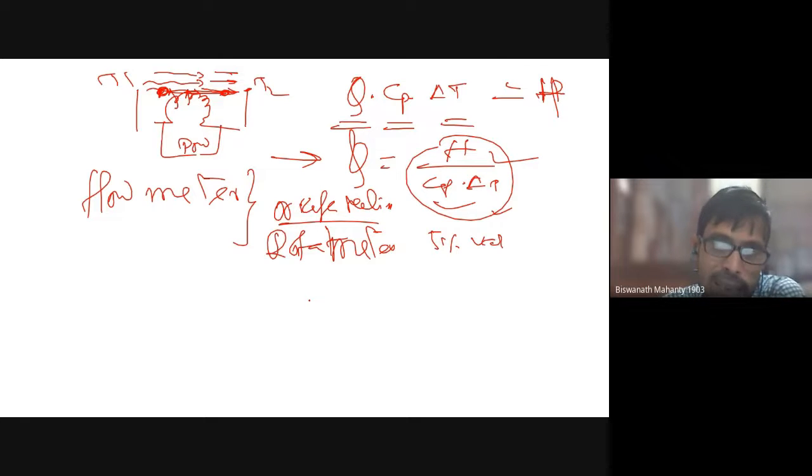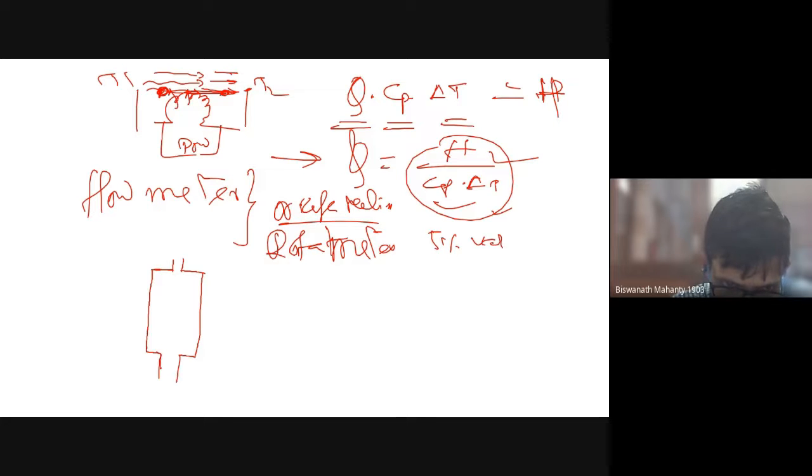Design is very, very simple. Now, how does this rotameter work? If we want to know the liquid flow rate, it is very simple. Let me show you. This is, for example, a glass connector. This is a glass chamber, right? Glass or Pyrex glass, whatever you want. And there is one big lightweight, not very heavyweight, cone or ball. Essentially a cone.